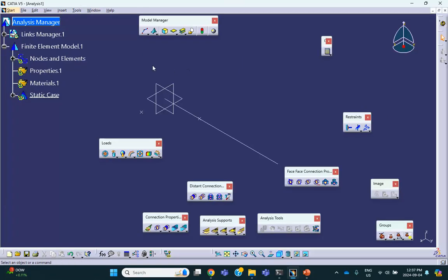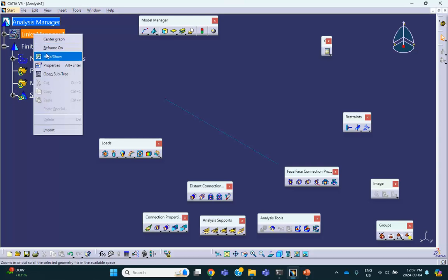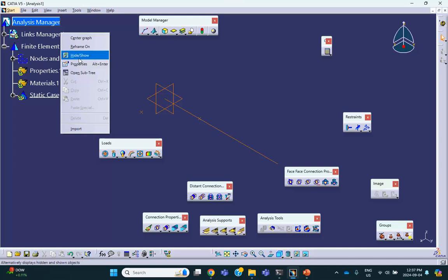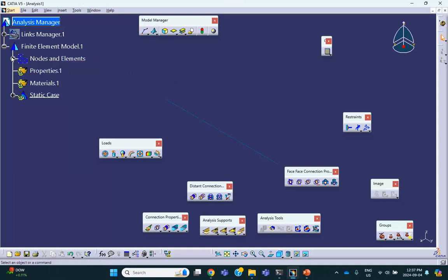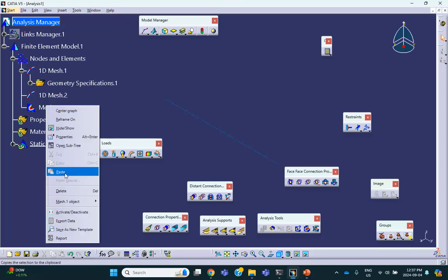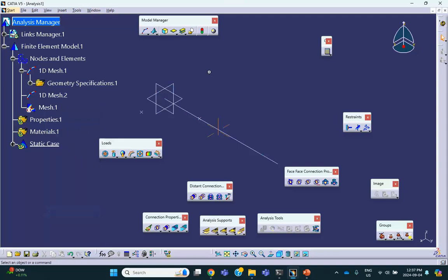In fact, if you say show me the mesh, it shows you both of them are going to be present, and that point, if I say hide and show, that point is going to be actually a node location. Oh, let's deactivate this. See what it did? It took that point, projected it into the line, and made sure that it's going to be a node. That's what this thing is saying. Right click, hide it or deactivate it. Okay, good.